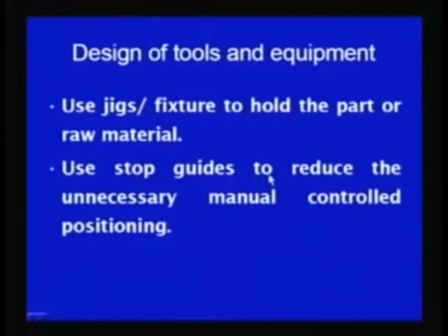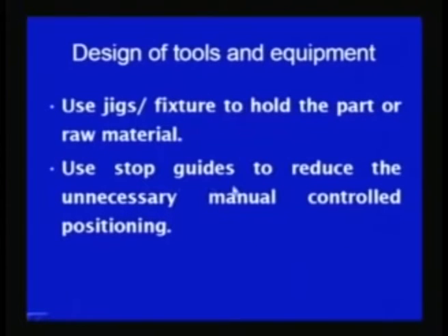Use stop guides to reduce unnecessary manually controlled positioning. Stops should be used as and when possible, so that manually it will not be required to start or stop or control the motions as per requirement. The system will automatically respond if stops and guides are used, and that will help to avoid unnecessary manually controlled positioning of the tool or of the workpiece during the operation.